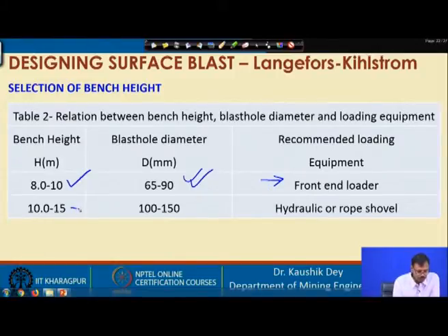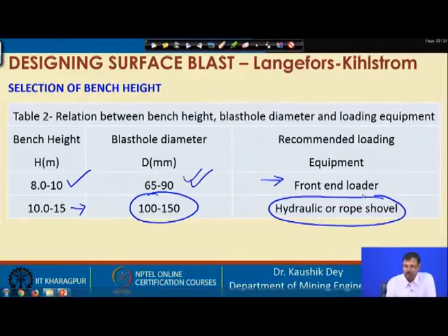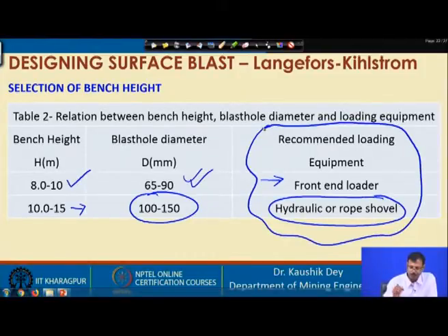However, in case of a little bit larger bench height, we have to select a little bit larger blast hole diameter, then the shovels may be a good equipment for the loading machine. However, this is the practical easiness of the handling of the material. If the material is very strong, very abrasive, and of high specific gravity, the front end loader may not give sufficient digging force, because the digging force of the front end loader is very limited.